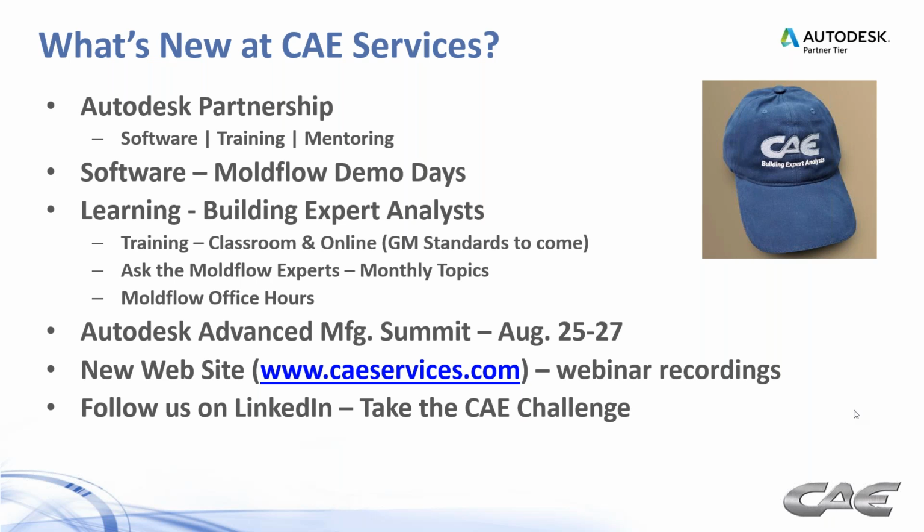Last question is, how can we trust Moldflow warpage results? Well, again, I'll just keep reiterating. Have an expert analyst. Make sure they understand tooling, make sure they understand processing, make sure they've got some experience at the press, so that the types of things that they're recommending make sense in all of those arenas.